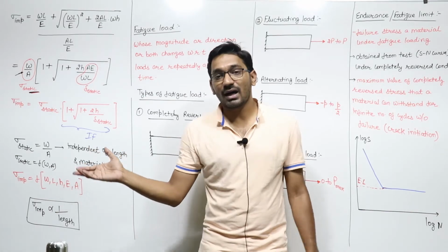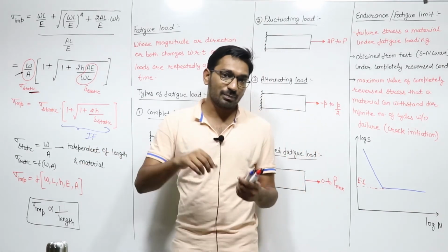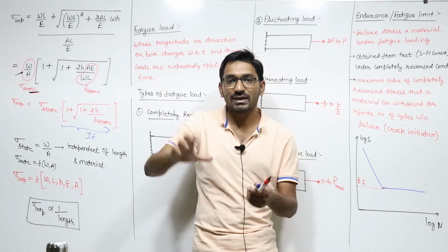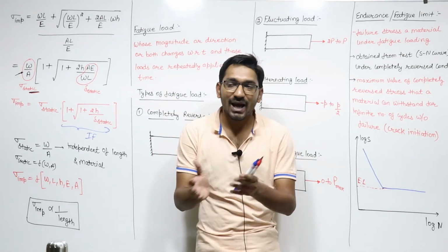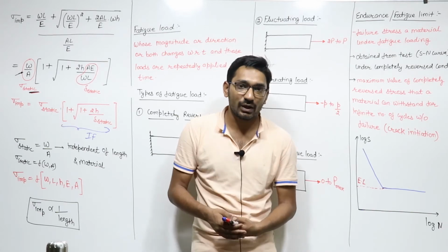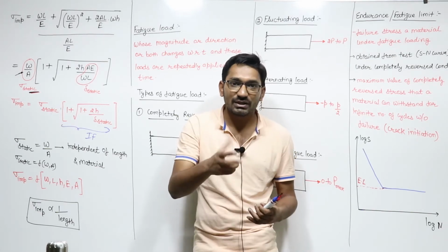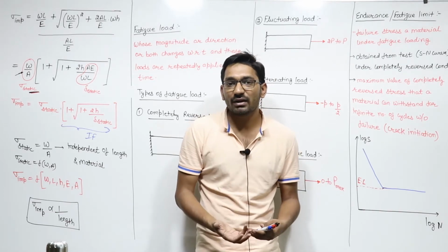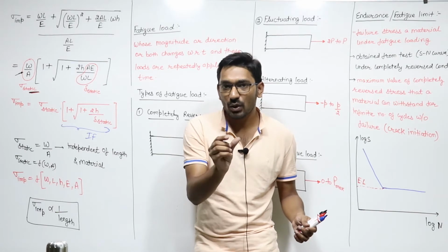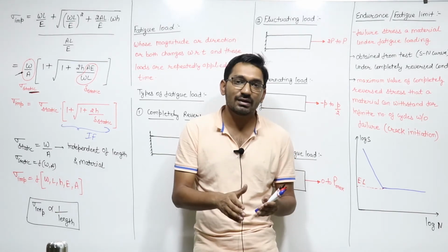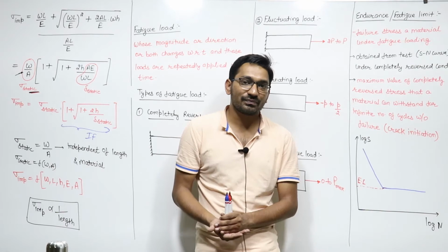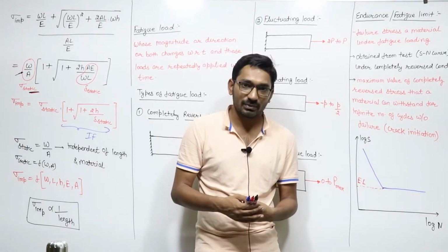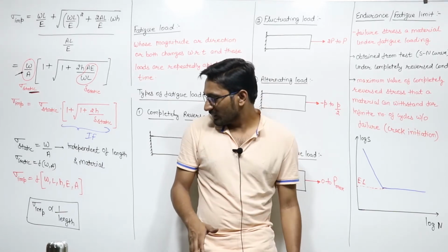That is the reason the length of the bolt is large, to make the bolt safe under impact loading. You know that we are using the bolt, and if this bolt is under impact loading and you make its length very small, then that bolt will fail. So that's why we make the length of the bolt as long as possible, right?